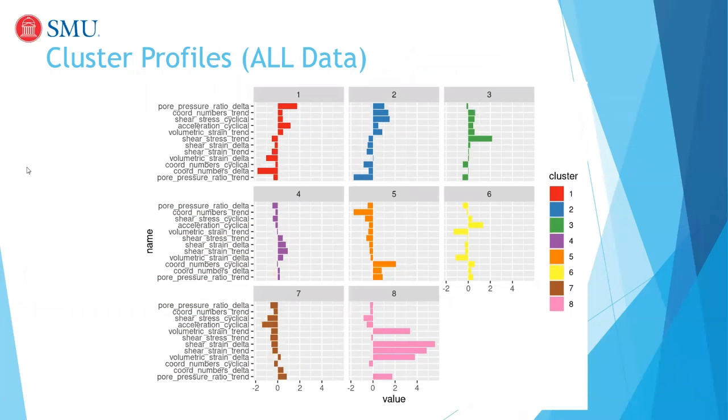And if we look at what is so distinctive about it, it's marking significant volumetric strain and shear strain, which we know, but it's very interesting to see that there is a tool that can capture that from our data. It gives us confidence that this technique is actually working. Because even though this is an advanced technique, we are applying it on, if you wish, a one-dimensional problem. It's just a soil deposit.